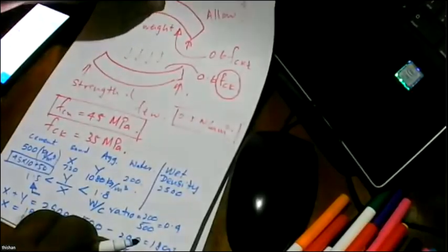And if you look at the strength development curve, because we know the main ingredients are C3S, C2S, C3A (tricalcium aluminate), and tetracalcium aluminoferrite, in the earlier days these were about 50%, 25%, 8 to 10%, and an impurity of about 10%.